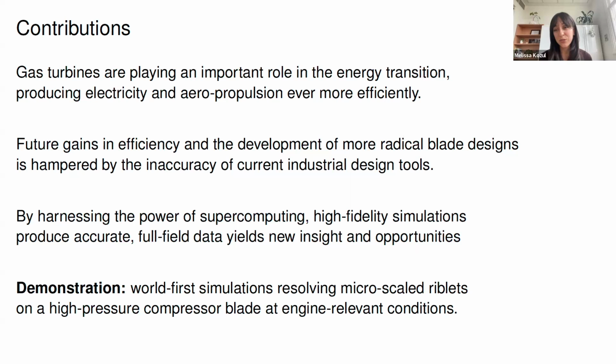That was also why we used the rounded bottom for the riblet and not a sharp bottom, because we thought, if there's some fouling, that's more representative of that. Turns out the trough of the riblet is not so important. It's more that spacing, because not much of the flow seems to get into that trough anyway. But fouling in the gas turbine is more a problem, and roughening of the surface on the high pressure turbine. So that's what my colleagues have studied.